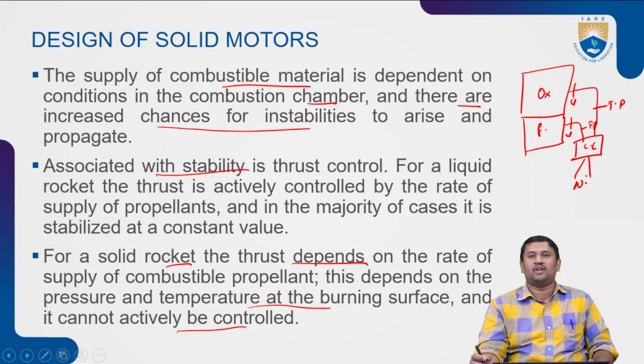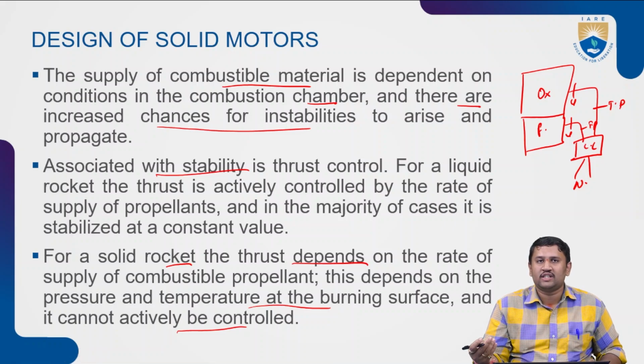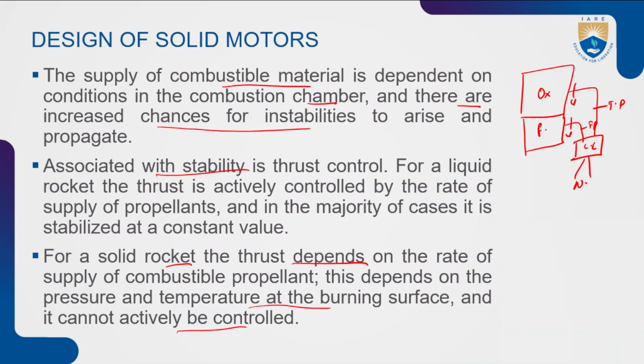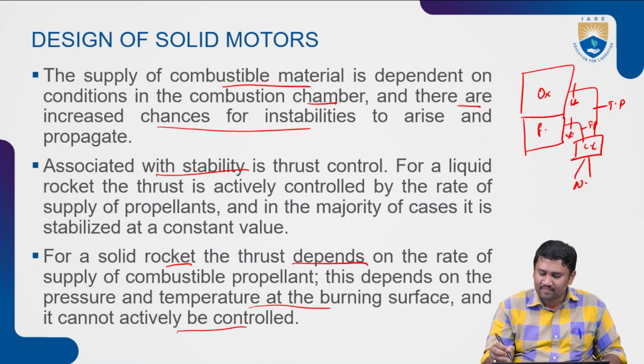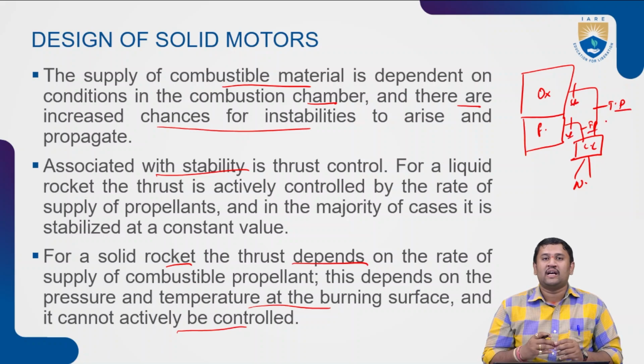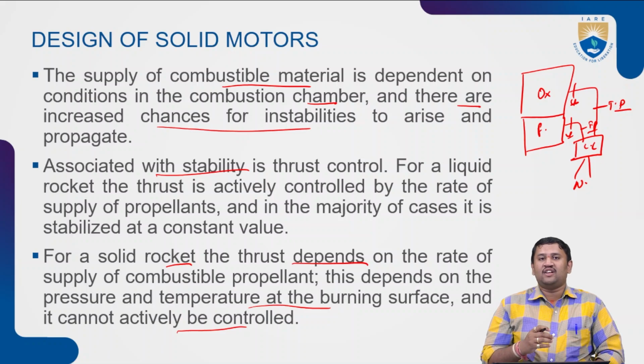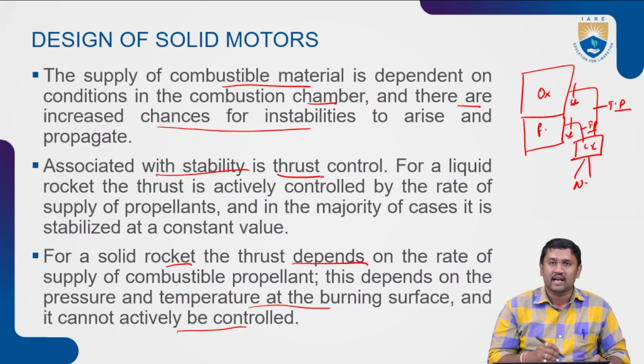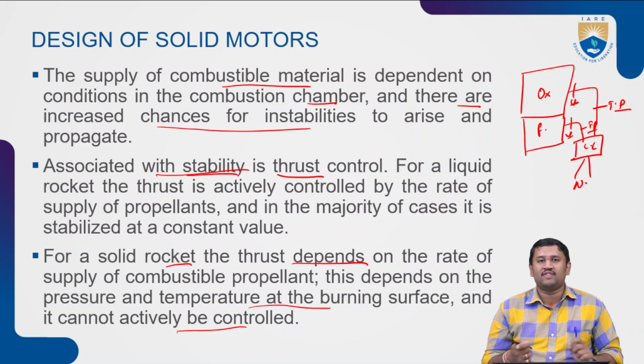nozzle. Now, what happens with respect to my liquid fuel engine is, whenever we are designing, we will have some elements, particularly the valves, the turbo pumps, and the piping to carry the liquid fuel as well as the oxidizer towards the combustion chamber. We can control the valves and the speed of the turbo pump to have a certain degree of freedom to control the amount of propellant entering the combustion chamber. That in turn directly controls my thrust as well as the stability of my aircraft as and when required.